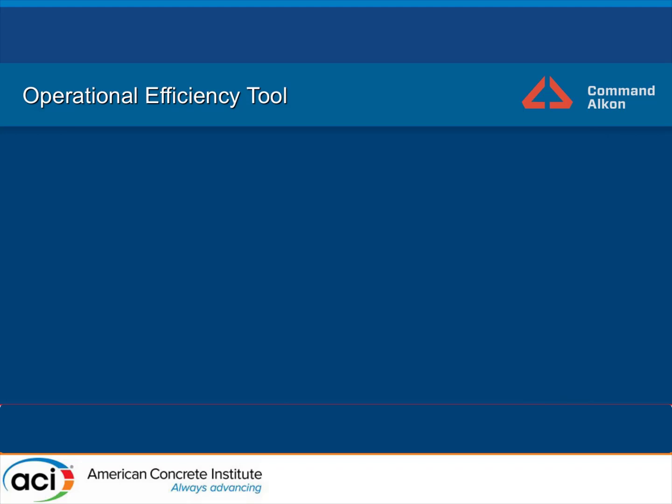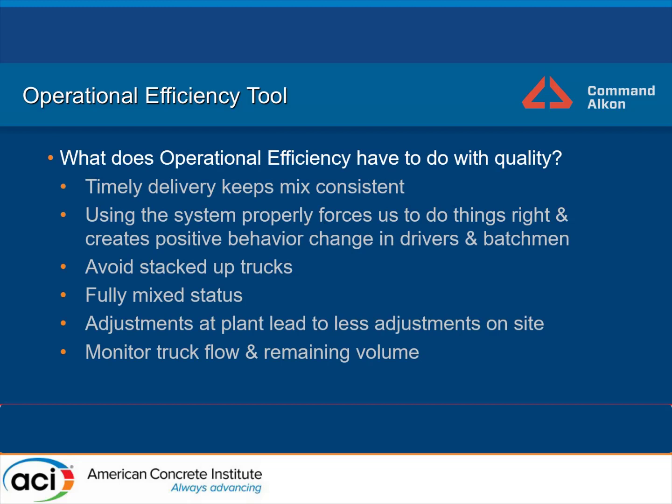Operational efficiency tool, probably not a highlight for the engineering community, but it is important to me as a ready-mix producer. What does it have to do with quality? Well, timely delivery is what gives us a higher quality. If we have to wait to adjust the loads or make adjustments, if we see the staging of the trucks using this tool, it forces us to do all the right things, forces us to take the proper moisture readings in advance, use the proper moistures, know what added water is being used.